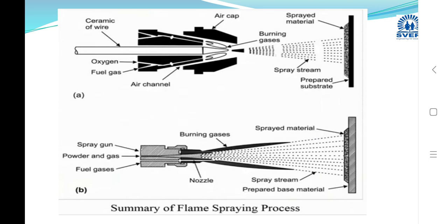In this case there has to be provision for a powder feeder so that the powder gets fed properly into the flame tip. And here you should have provision for ceramic wire or rod to get in, get melted, and the molten material is subsequently spread over the surface.